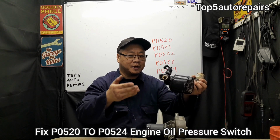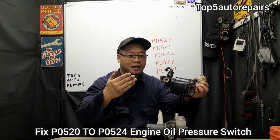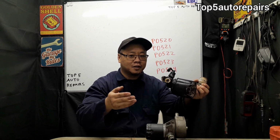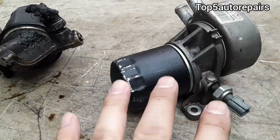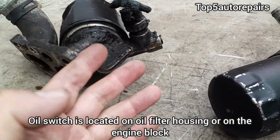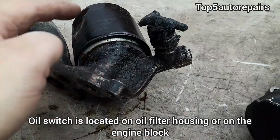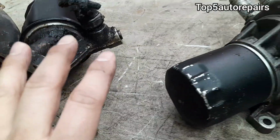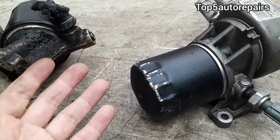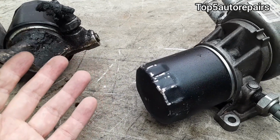How do you fix P0520 to P0524 oil pressure sensor switch or sensor trouble codes? So the oil pressure sensor switch or sensor is usually mounted on the oil filter housing or is mounted somewhere on the engine block, usually on the side of the engine block.